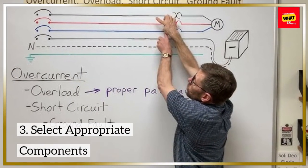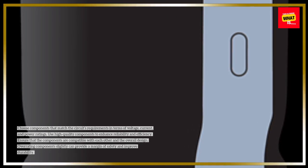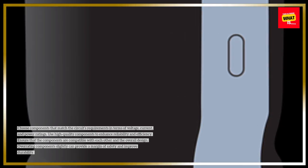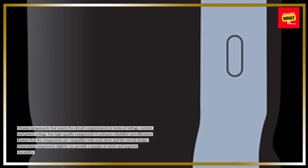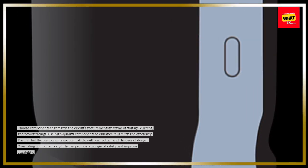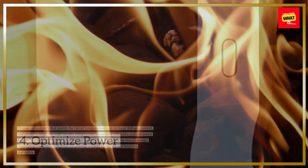3. Select appropriate components. Choose components that match the circuit's requirements in terms of voltage, current, and power ratings. Use high-quality components to enhance reliability and efficiency. Ensure that the components are compatible with each other and the overall design. Overrating components slightly can provide a margin of safety and improve durability.